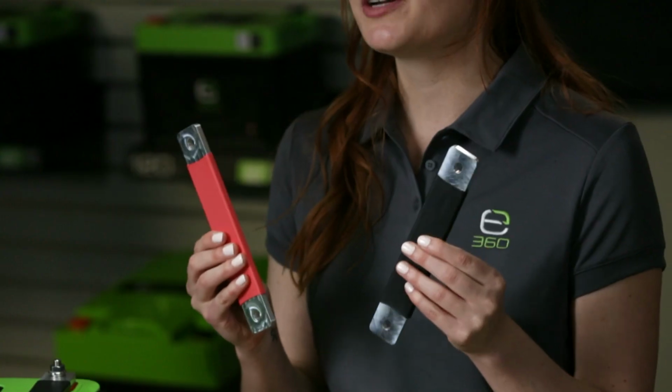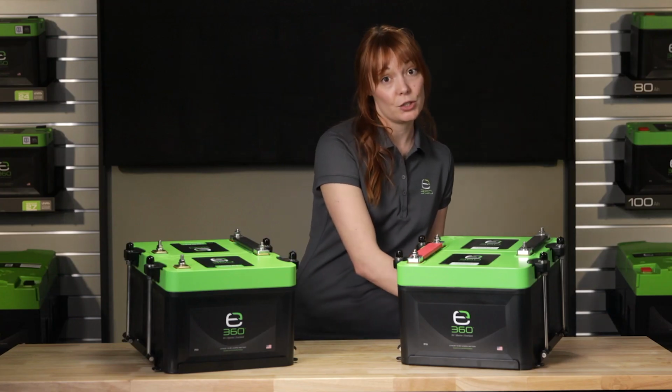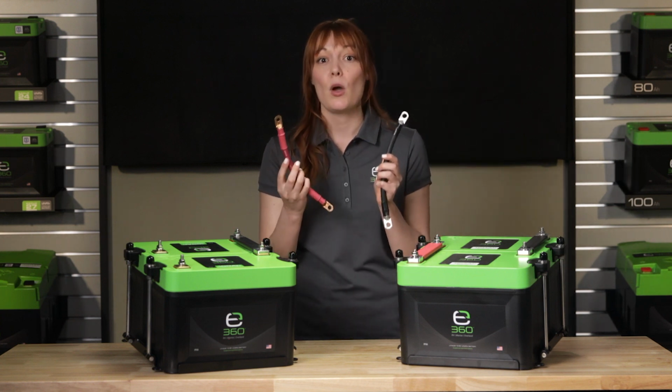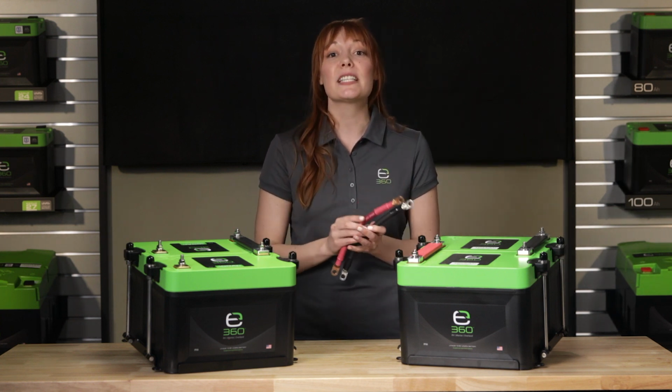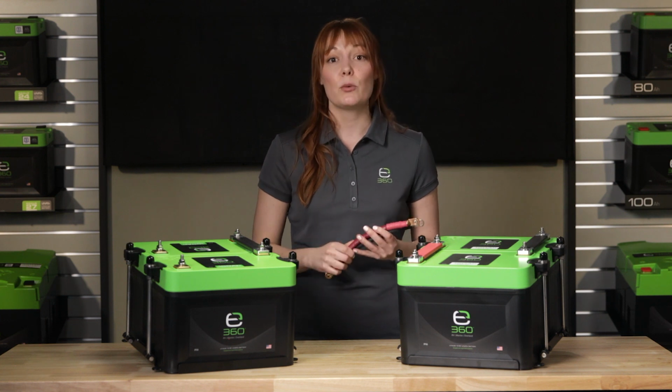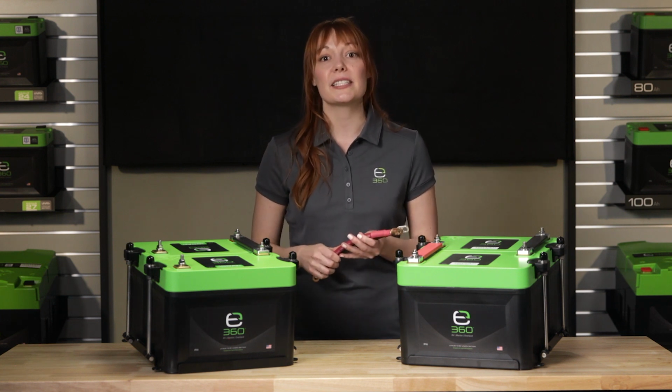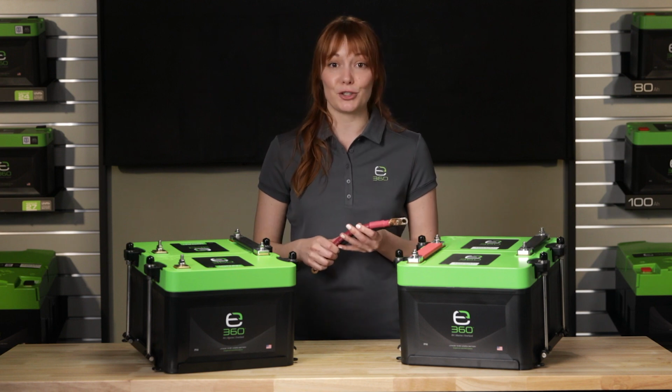Bus bars are your preferred method of connection, as opposed to interconnecting wire-type cables. Wire interconnections are susceptible to loose connections, loose lugs, and unequal lengths, all of which add up to additional resistance, resulting in heat and higher voltage drops.